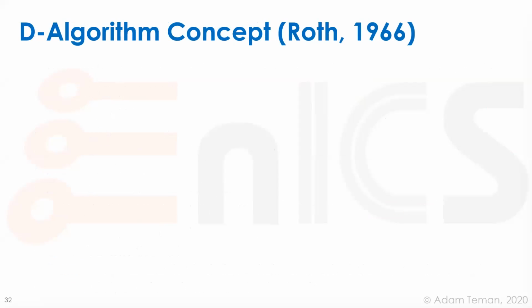The famous algorithm for doing this, rather than sticking in the fault and checking all the vectors to find out which vector would actually do it, is this: our ATPG tool, our automatic test pattern generation tool, is going to make a bunch of random vectors and little by little remove faults from the dictionary and see what our coverage is.